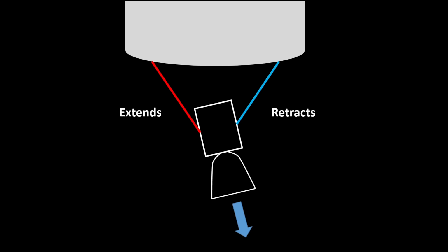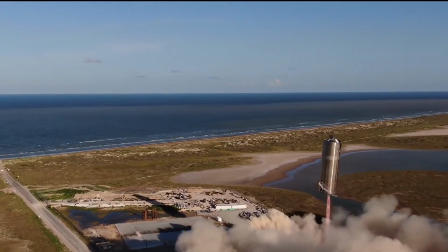Now the exhaust is pointing away from the center of the rocket and can be used to either create horizontal movement or a lever arm to flip the vehicle around. And due to the triangular setup, the engine can theoretically be pointed in every direction to a certain angle. The Raptor has the ability to gimbal a whopping 360 degrees. But in operation, that is